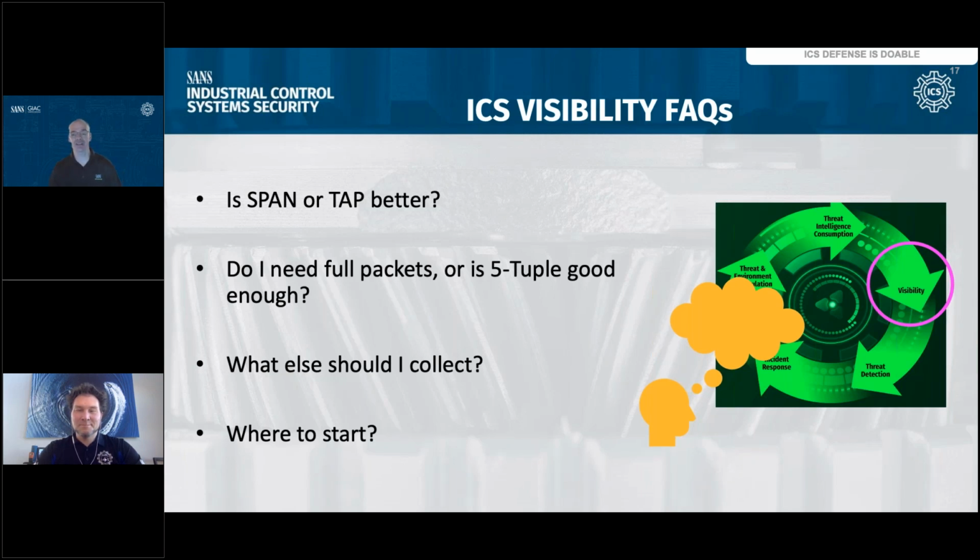But there are some things to consider depending on what your situation is. And I should add as well that when we get down to the field bus level, to the non-IP protocols, it's a different conversation. You may still be able to get something like a span port out of a field bus switch, but we are now having a different conversation at that point. And that traffic is interesting to see, it's valuable. It's next on my list. I'd like to see anything that's coming down into that level to have an impact, and I'll worry about level 2 a little bit later.